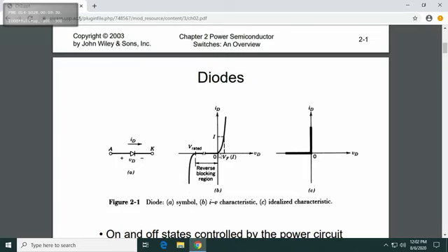Now moving towards the positive side, if we apply a voltage, it will start rising exponentially to a certain point, Vf, V forward. In normal cases, you remember our V forward voltage was 0.7 volts. So Vf is rated. For power diodes, you'll have different values of Vf, so make sure you look at the ratings for this in the data sheet. Once you reach the V forward point, your current will increase according to the voltage value of your supply.